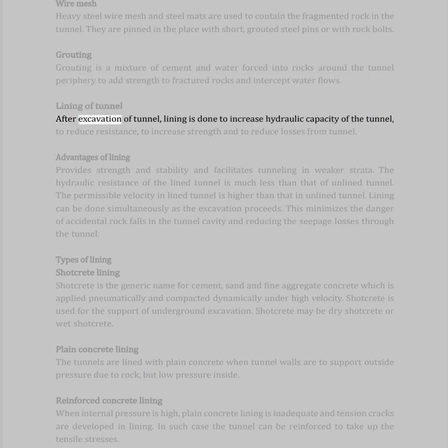Lining of tunnel. After excavation of tunnel, lining is done to increase hydraulic capacity of the tunnel, to reduce resistance, to increase strength and to reduce losses from tunnel.